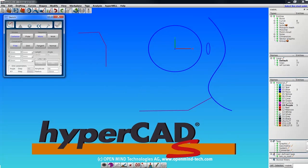You can also create arcs with the sketch command, but only in multi-mode and only after creating a line first. And you can select the arc option, specify the radius and the amplitude, which is the angular sweep of the arc, and then you can continue with a tangent line or a tangent arc.